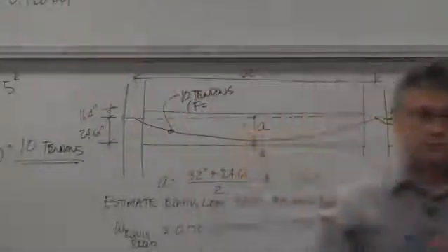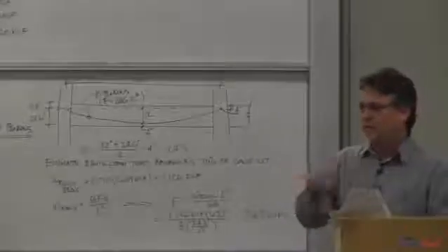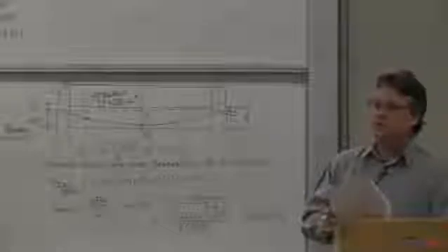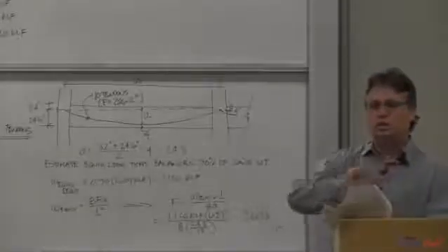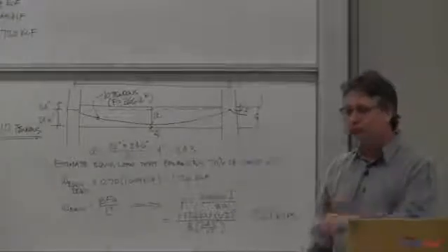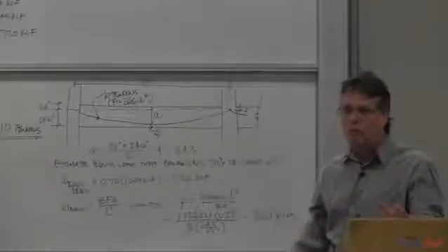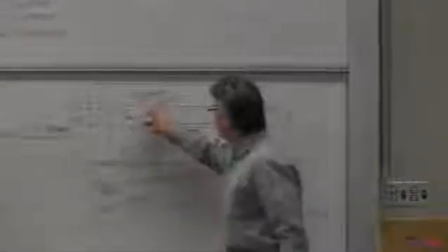What's the force? It's not 267. Don't write fails or no good or need 11 tendons. I get this every year, and some people will really struggle with what is just an approximate starting point. We're just getting close. The closest number to giving me 267 was 10 tendons. It gives me 266.2. I'm approximately 70% of the dead load. There's nothing magic about being 70%. If I'm 69.3%, that's just fine. There's no code requirement. Nothing fails. Nothing's wrong. You're doing these things to come up with the closest approximation.